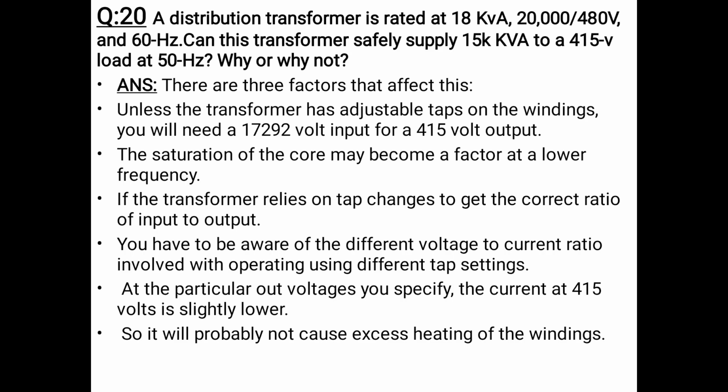Number 20. A transformer is rated at 15 kVA, 20,000 over 480 V, and 60 Hz. Can this transformer safely supply 15 kVA to a 415 V load at 50 Hz? Why or why not? Answer: There are three factors that can affect this.